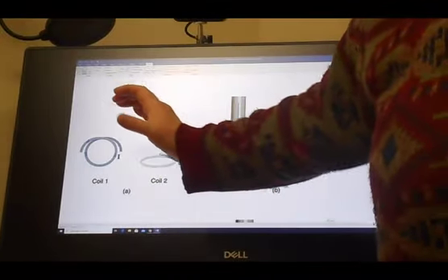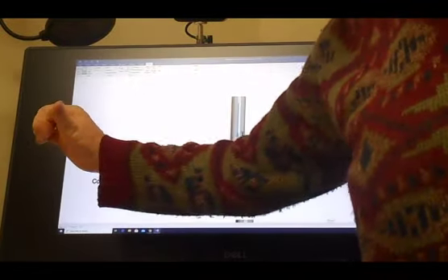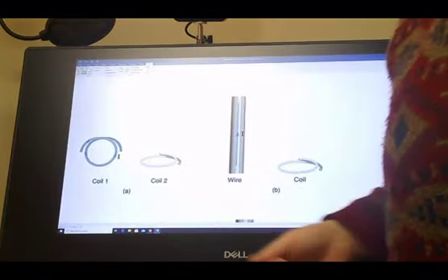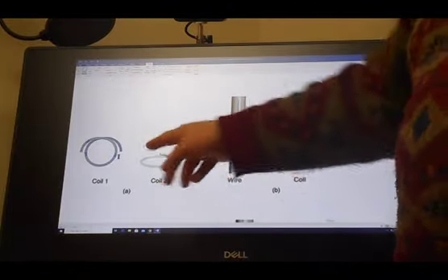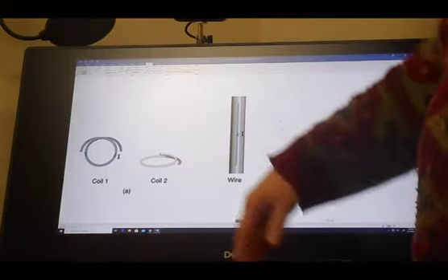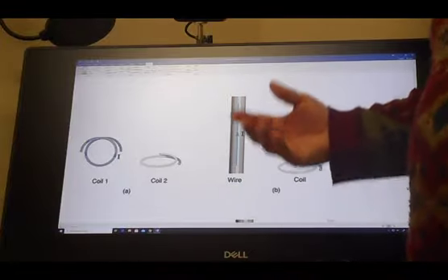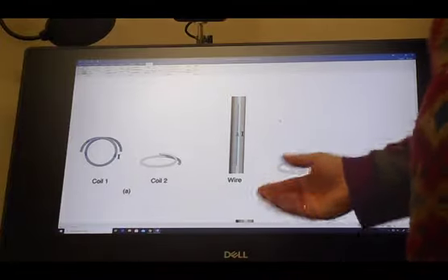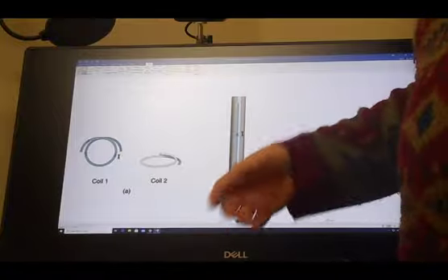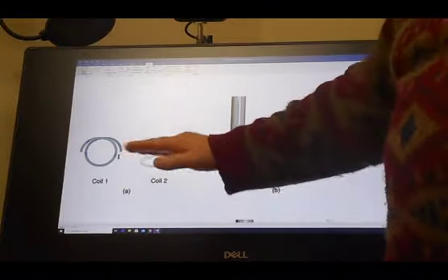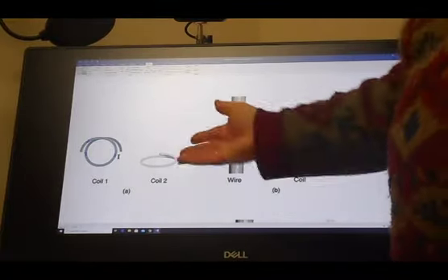So this one here, magnetic field, current curled, magnetic field pointing this way, which means this one wraps around now like this, so the magnetic field is going this way. And no matter if it's constant or if it's actually changing, so if we have a changing magnetic flux here, it's bypassing that coil, and you can see that from the equation. The angle between the two is 90 degrees. The magnetic flux takes on the cosine of the angle, so cosine of 90 degrees is 0, and no matter what is happening here, current increasing and therefore magnetic field increasing or decreasing or constant, doesn't matter, it's all bypassing that coil and you don't get anything here. So it's simply just 0, nothing will happen here.